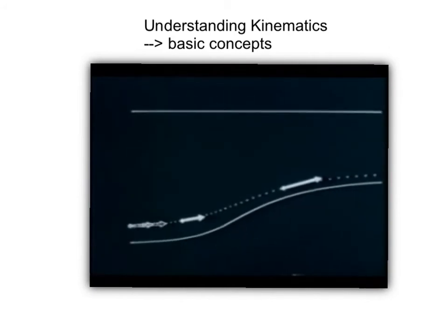Although the physical field is the same, the Eulerian and Lagrangian representations are not the same, because the velocity at a point in laboratory coordinates does not always refer to the same piece of matter. Different material points are continually streaming through the same laboratory point.